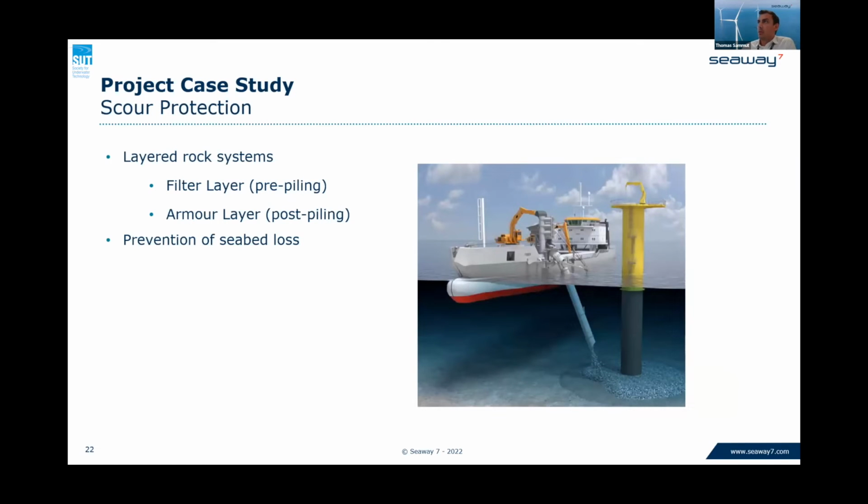One thing to keep in mind with the schedule and the logistics is typically some foundations or all foundations will require scour to prevent seabed loss. And depending on the type of system and technology, you can have filter layer, armor layer, and that will come before the piling. So in this case, you have to think about the HLV and when its availability is planned, and then make sure that there's no bottlenecks in available locations to start installing before the scour is installed.